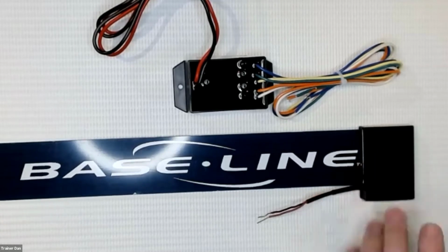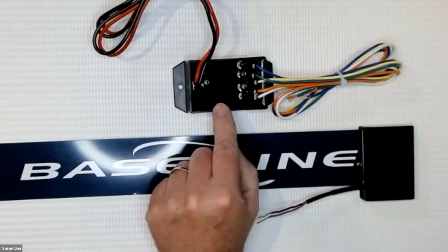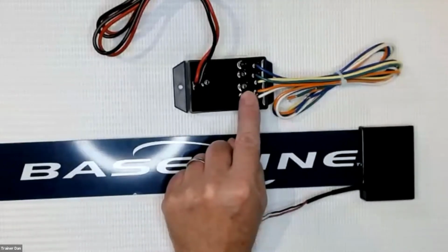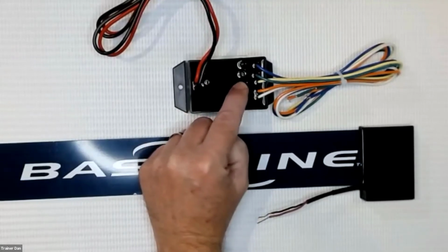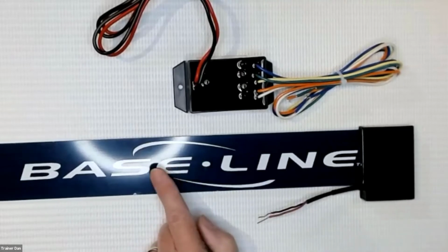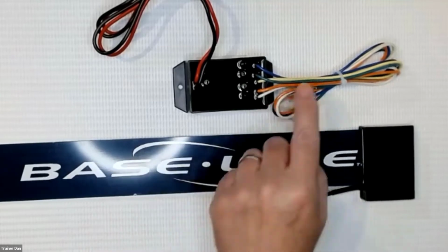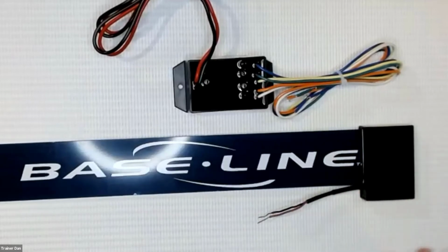Yeah, the controller will give us error messages and tell us what's going on. We'll look at those in a minute. It would tell me if I have an open circuit on the second zone, or a short circuit on the fourth one. It'll give me information, or it might tell me that I'm reading temperature but not moisture content. There's a problem with this device. Or it might tell me that there's a communication error or a wire problem here. Lots of information will come with the controller.